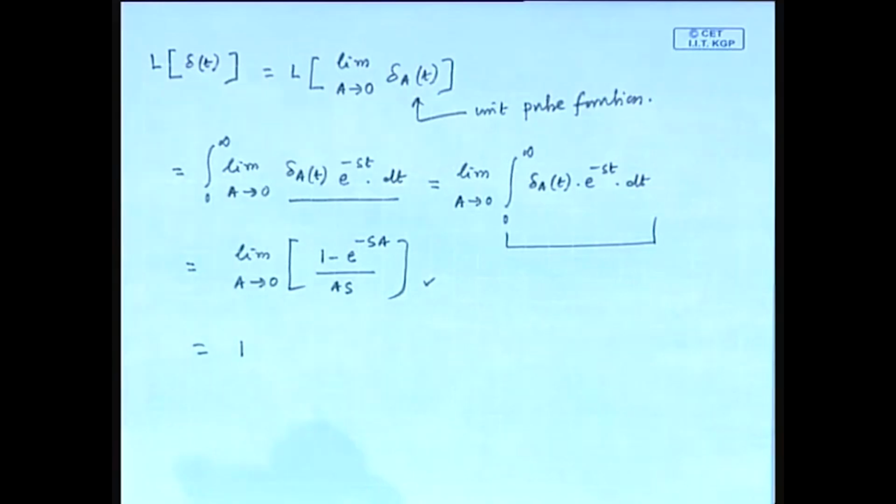Can you give any example of this unit impulse function? I mean, we can continue the same example. Say we have one steam valve. Can we give the example of this impulse function? It is impossible to realize perfectly, but we can give an example like this: open the steam valve and instantaneously return to the old value. Open the steam valve at t equal to 0, and as soon as physically possible thereafter return to the old value. This is the example of an impulse function.